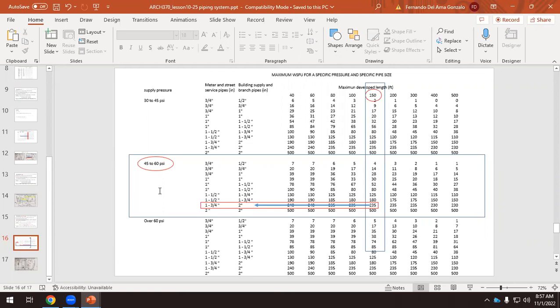Yeah, well, if we're not sure, yeah, we can check it. Okay, let's see. Oh, because here we don't have 5 toilets. We have in each restroom 10 toilets and 10 sinks, and we have 4 floors. Okay, do it. But for 2-floor buildings with 4 restrooms, 2 inches. So I bet that the final result of your Revit file will be 2 inches.